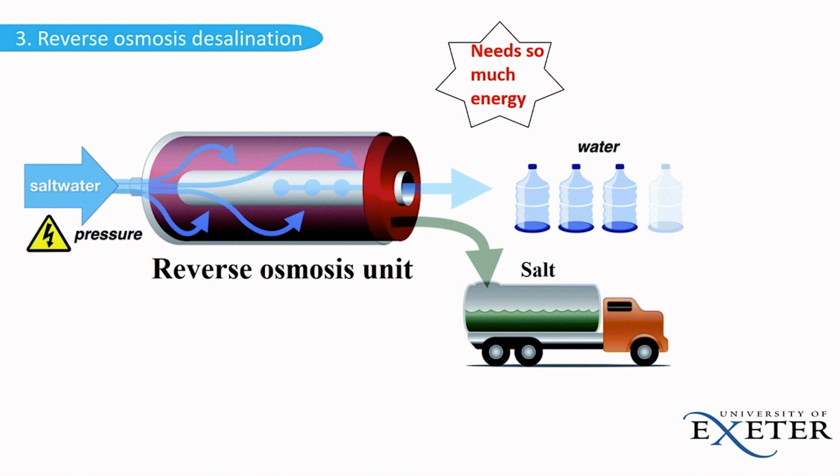Right. One of the common desalination methods is reverse osmosis. You can see a schematic of a reverse osmosis desalination unit here. Reverse osmosis is a process where pressurized seawater flows through a filter, separating fresh water from saline water. By adding an external pressure to one side of the filter, clean water will flow to the other side. The product of the reverse osmosis process is fresh water and the brine with high salinity.